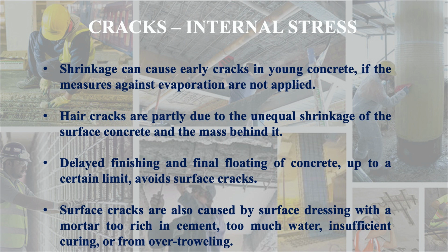Surface cracks are also caused by surface dressing with a mortar too rich in cement, too much water, and insufficient curing, or from over troweling. These may be the reasons for surface cracks.